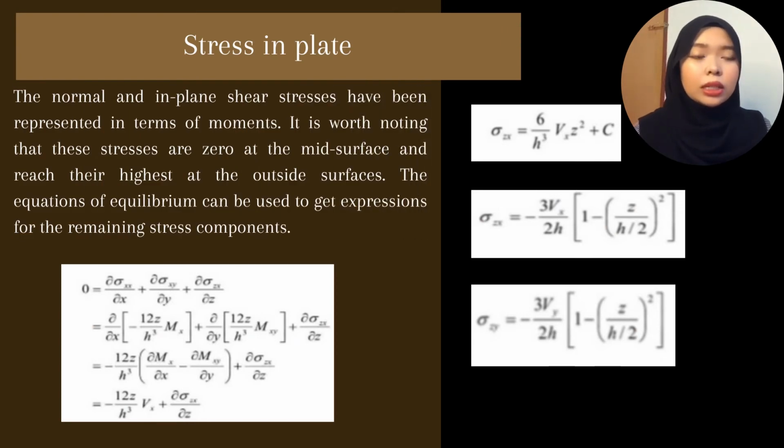So, this is the stress in a plate. The normal and in-plane shear stresses have been represented in terms of moment. It is worth noting that these stresses are zero at the mid-surface and reach the highest at the outside surface. The equations of equilibrium can be used to get expressions for the remaining stress components. So, this is the formula that we always use.